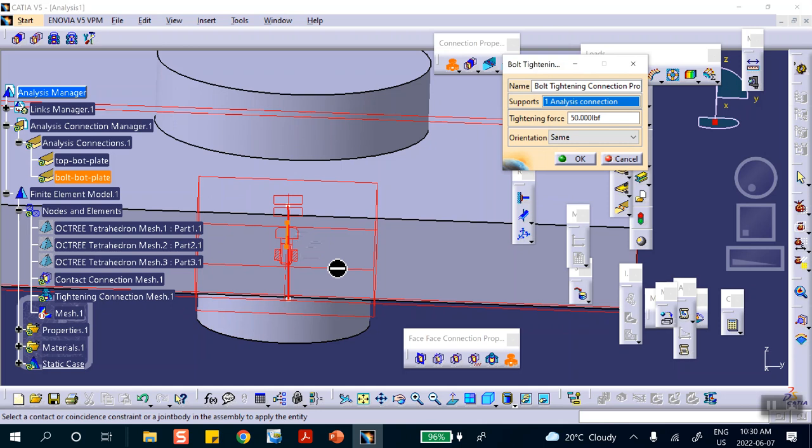In other words, put the bolt from the top. If you try the other direction, opposite, that guy will flip. And one will work, the other one will not. My experience is that this one is not right. It will run, but the thing will not actually tighten together. So I'll do it exactly the way I wanted it, like this.